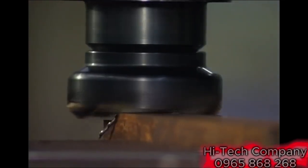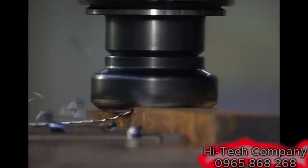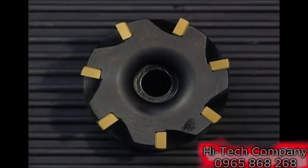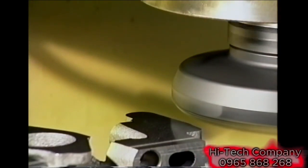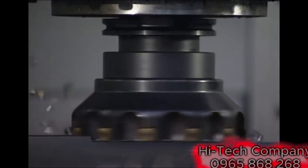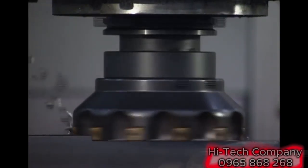Gullet size is important in face milling, since the chips are generally confined to the gullet until the insert exits the cut. Cutters may be coarse pitch, fine pitch, or extra fine pitch. Fine pitch cutters are used primarily for milling cast iron or for finishing work. Coarse pitch cutters provide a large gullet space necessary for milling ductile materials or in wide cuts. They are chosen for everyday work.